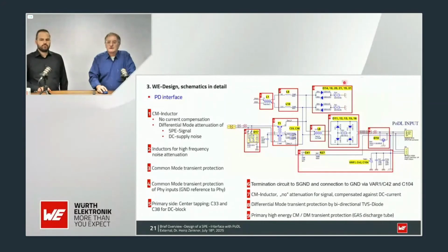Why? Together with the parasitic capacitances of these silicons, you have a low pass characteristic. And this gives you the possibility, with a limited filtering with capacitors, to have quite a good working reduction of radiated and conducted emission.